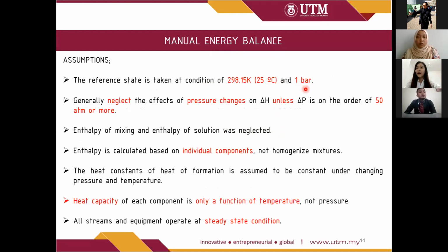these are some assumptions made in the energy balance calculation. In the assumptions, we neglect the effect of the pressure change on the enthalpy if the pressure change is small. We also neglect the enthalpy of mixing and enthalpy of solution, and the enthalpy is calculated based on the individual components only. And most importantly, all the streams and the equipment are assumed to operate at steady state condition. So next.